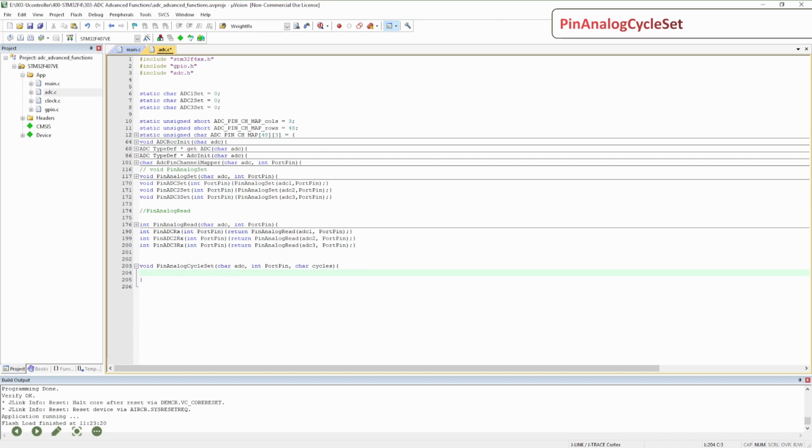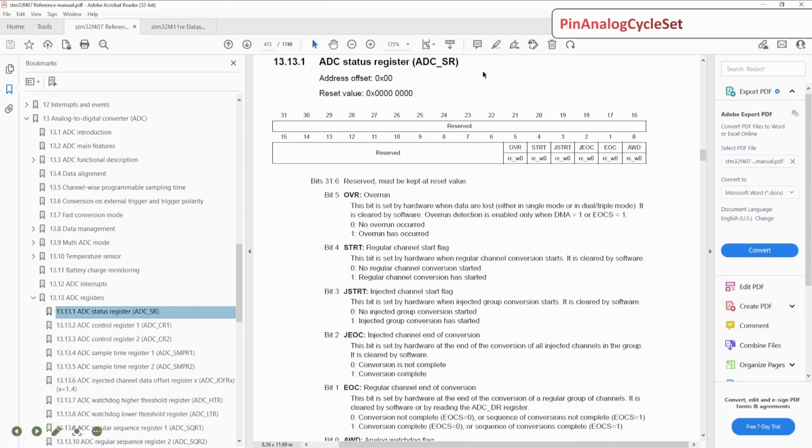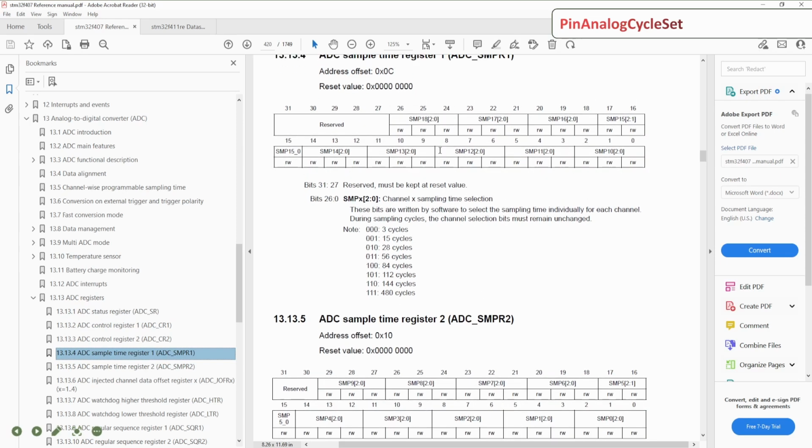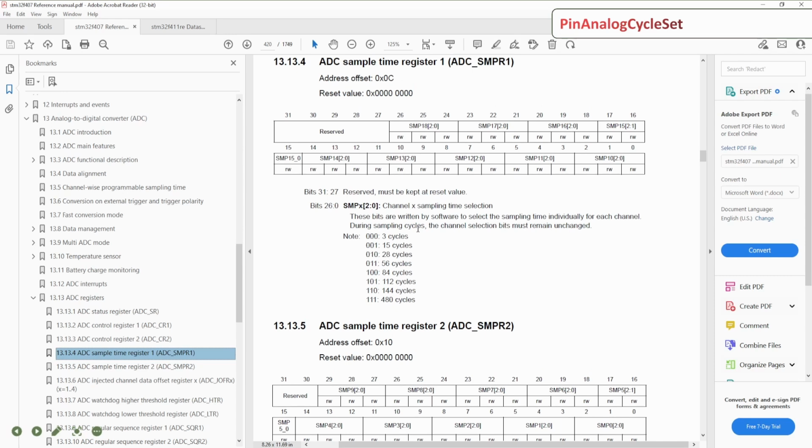And just to get back a little bit to understand how this is working, let's go to the STM32F4 ADC registers, and we go here. So those are the registers. There are two registers that control what they call the sampling rate, so the number of samples that the ADC will perform before delivering or flagging the end of conversion.